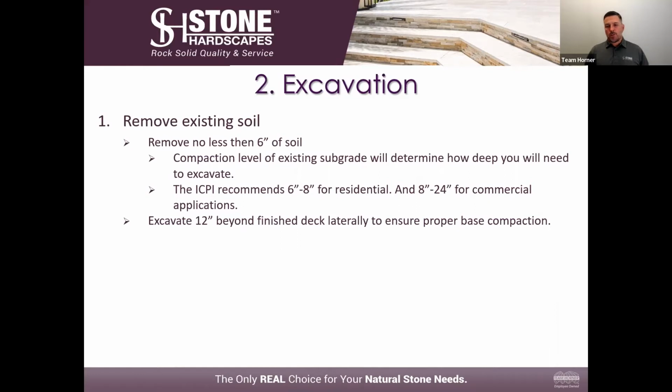For residential, you're 6 to 8 inches. For commercial, you're 8 to 24. Laterally, when you excavate, you want to excavate about 12 inches outside of the deck area itself. That helps you run your base material farther out and gives you a really solid foundation to lay your pavers onto.